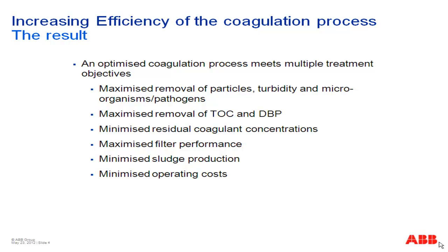Where people manually coagulate on surface treatment works, especially in today's times where plants haven't got 24 hours manning, we don't have full-time scientists on site. What will tend to happen when the site's unmanned, I've had this said to me by many process scientists, they will up the coagulant dose, they will put a buffer on the system. You can get away with putting more coagulant in than you require. You can't get away with underdosing, but you can get away with overdosing to a certain amount.